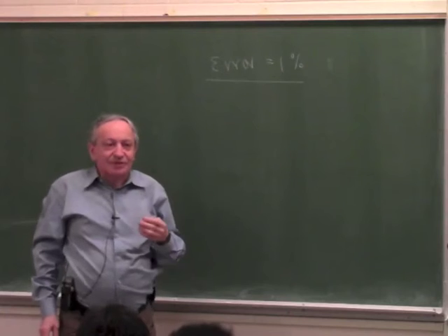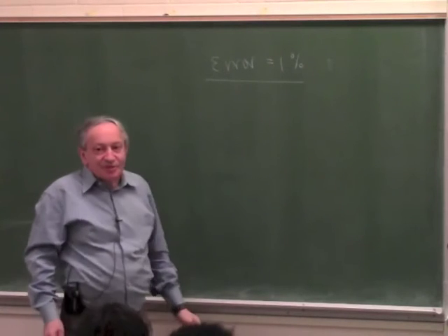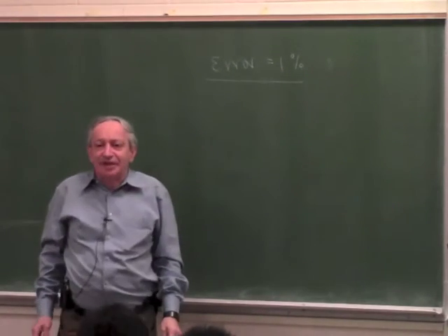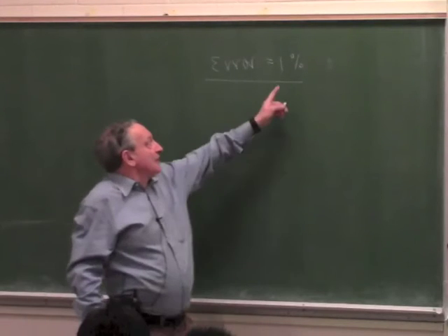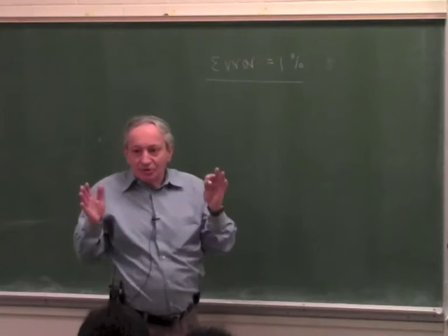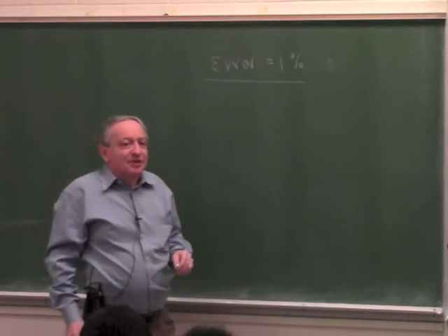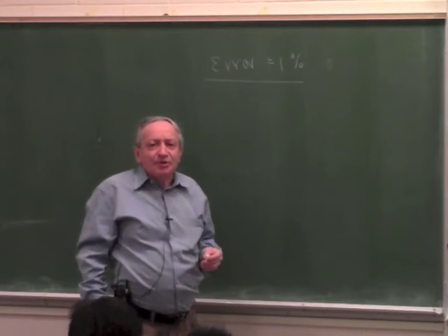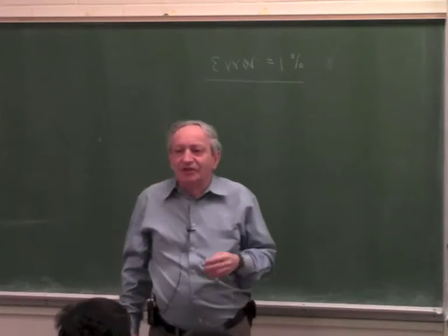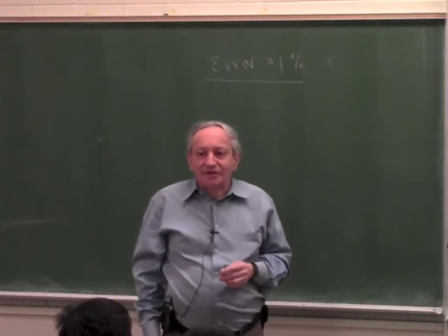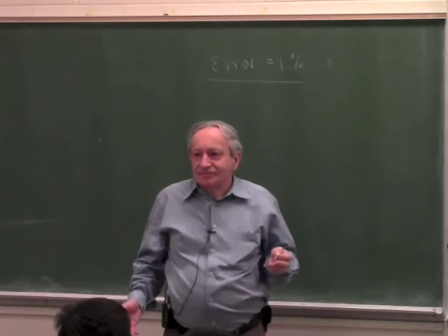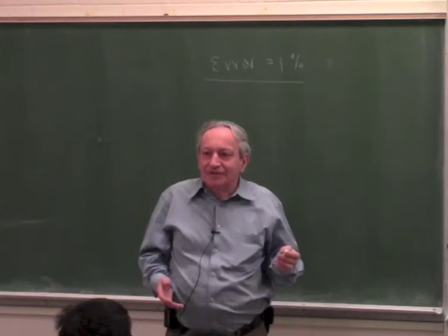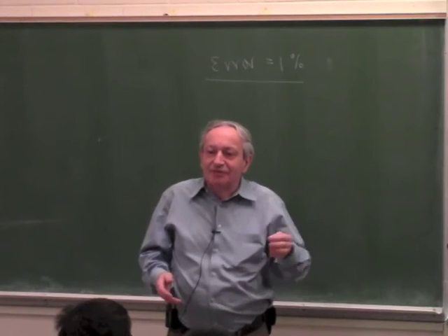That's also a common error of inexperienced designers, because they say 1% is 1 part in 100. So that's total error, not plus minus. Total error band 1%. So inexperienced designers say, okay, 1% is 1 part in 100, so how many bits do I need to have an accuracy of 1 part in 100? 7. 7 is 128, right? 8 bits is 1 over 256, 7 is 128.